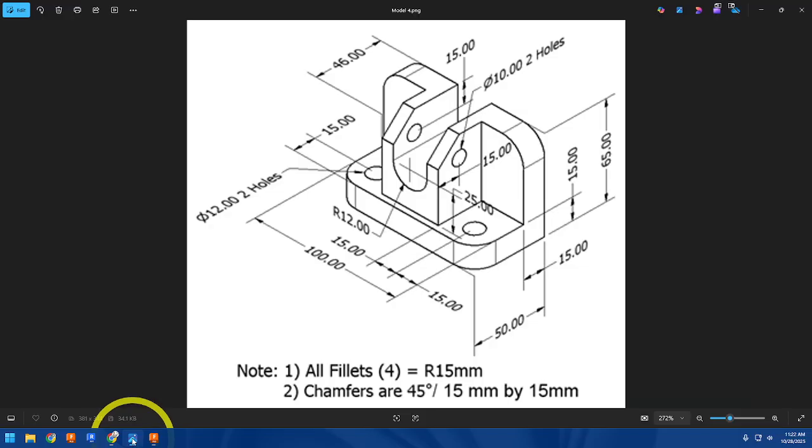When I look back at this, I've got two notches, one big notch on this side, one big notch on the left side. They do not give me the exact dimensions of that, but I know that from the front edge to the center of the circle is 15 millimeters, and from the center of the circle to the next edge is another 15 millimeters, so that's 30. The depth down that this goes is 65 millimeters, and then we have to take away this 15 for this surface right here, which would make that 50. So it's 30 by 50.